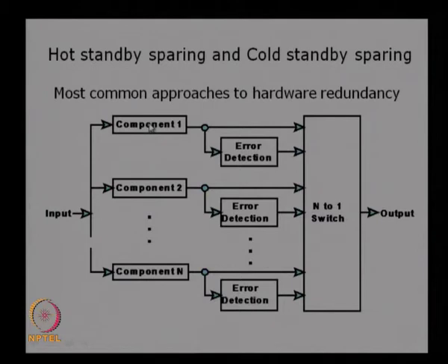Normally component 1 will be providing an output and component 2 and other components will not be providing any outputs, and whenever there is an error detection, immediately this will be started and the output will come from here and then go out as the output. So, there may be a small time delay between these two outputs. Since they are not in the hot mode, they are in the cold mode and need to be activated, so there will be a time delay in getting the output. That is the main difference between hot standby and cold standby.